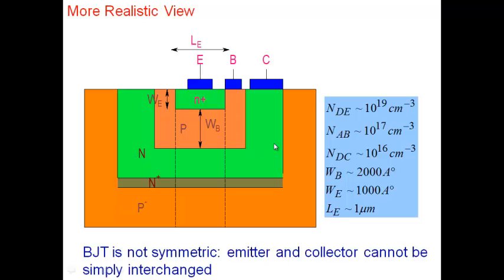So this is how the bipolar transistor actually looks. This is again a simplified version. Okay, how it looks. Now you see here the emitter that you see here is N plus. The base is here, P region here, and this is the collector here. Now, why do I need an N region and a P region and an N region here? NPN. I'm trying to make an NPN transistor. That's why we have N, P, and N region here.